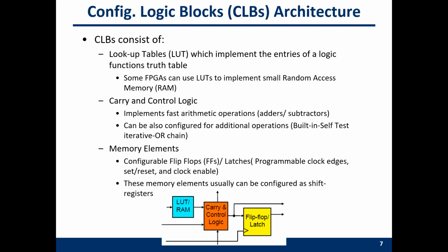So the configurable logic block consists of some lookup tables for your truth table. So these lookup tables can also be used to implement some RAMs. It also has a part for the carry and control logic. So by these components, you can implement very fast arithmetic operations like adders and subtractors.